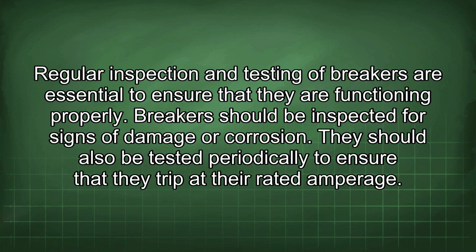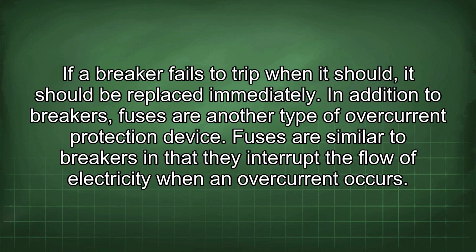Regular inspection and testing of breakers are essential to ensure that they are functioning properly. Breakers should be inspected for signs of damage or corrosion. They should also be tested periodically to ensure that they trip at their rated amperage. If a breaker fails to trip when it should, it should be replaced immediately.